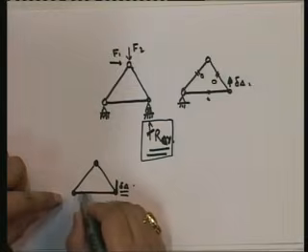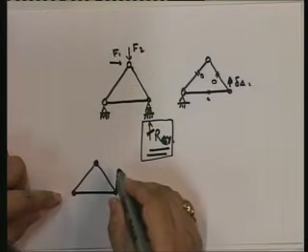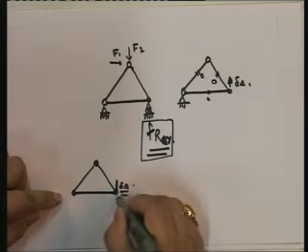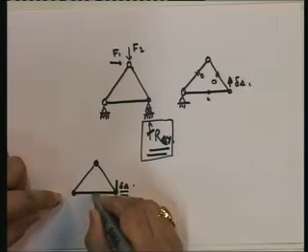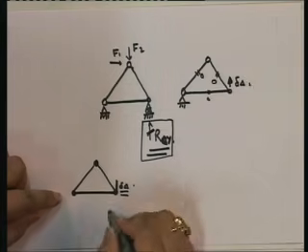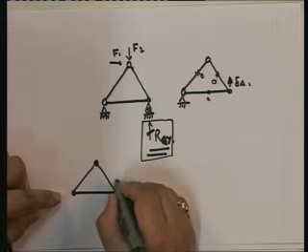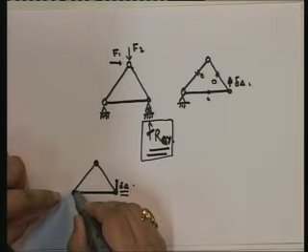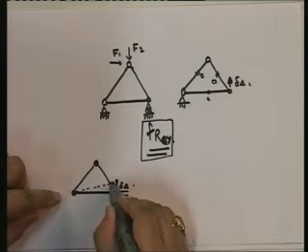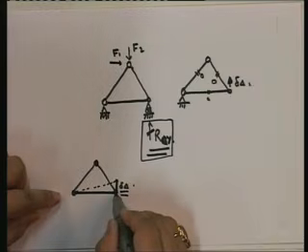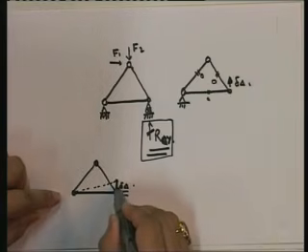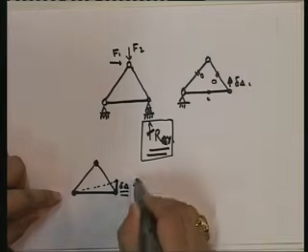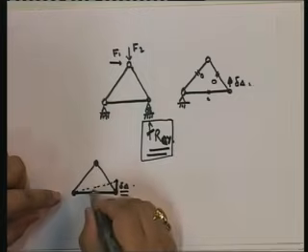So note that for this member not to actually deform, it is free to move in this direction, tangentially. If it moves in any direct direction, you're going to have axial deformation. So you cannot. That means this point can only move up here. I'm going to show this. It may look longer, but remember that this length and this displacement is very small compared to this length. So although it looks longer, it really isn't. It's just that I've exploded the view.